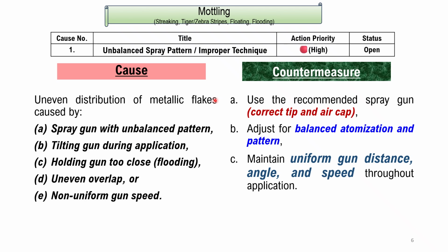The countermeasures recommended are: use the recommended spray gun, that is, correct tip and air cap, adjust for balanced atomization and pattern, and maintain uniform gun distance, angle, and speed throughout the application.